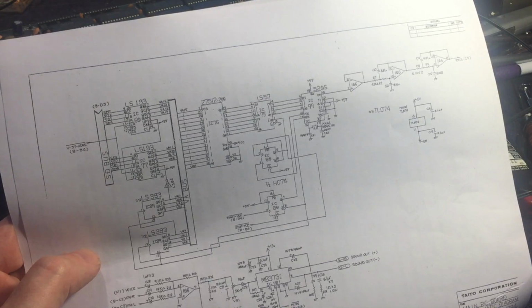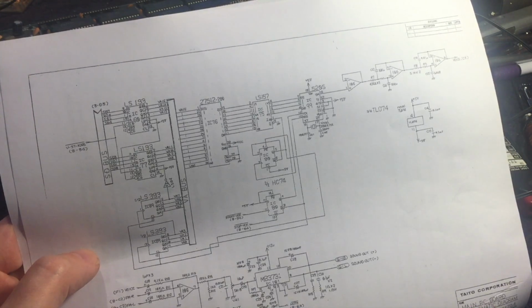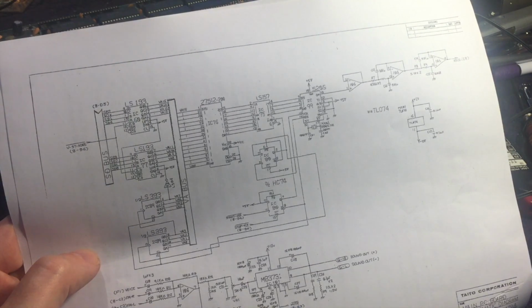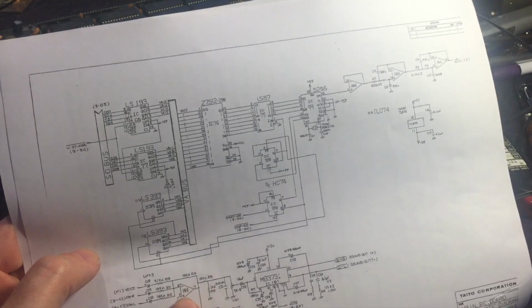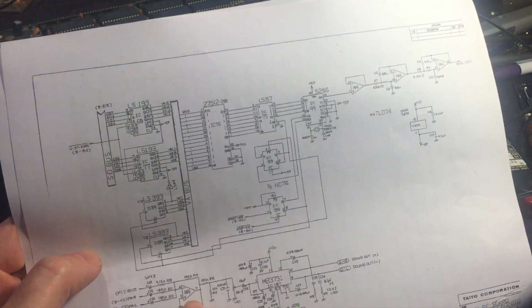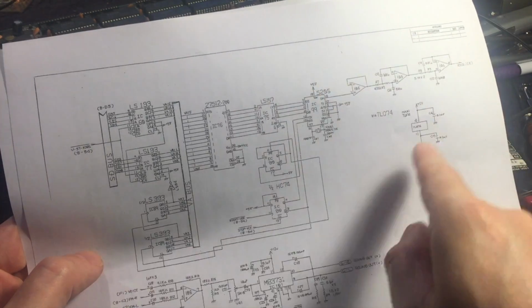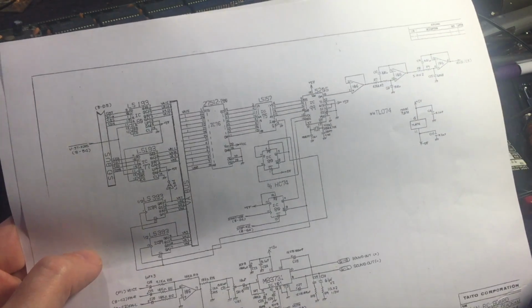So now, the fact that we're not getting any sound, either the music or the voice effects, means that for an analog problem, about the only thing left is this op amp here, the one that mixes all of the outputs. Because if any of the earlier ones are bad, we would get at least one of those types of sound, but we aren't.